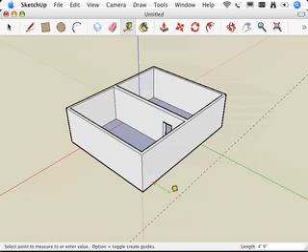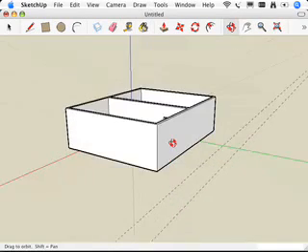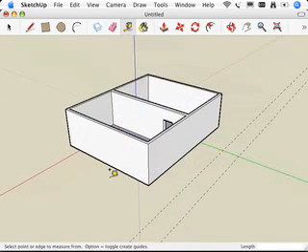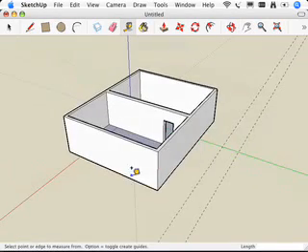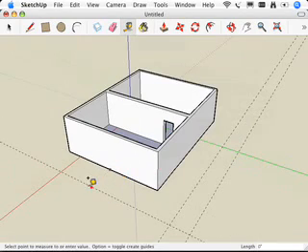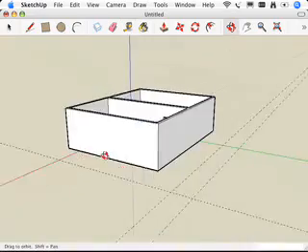But if I hit this in the middle of this operation, all of a sudden a guide will appear, and I'll have made a guide just like that. It's really as simple as that. Hit Control to toggle on and off creating guides with the tape measure tool. These guides that I was making so far have all been parallel guides, meaning I draw them parallel to the edge from which I click, I suppose.